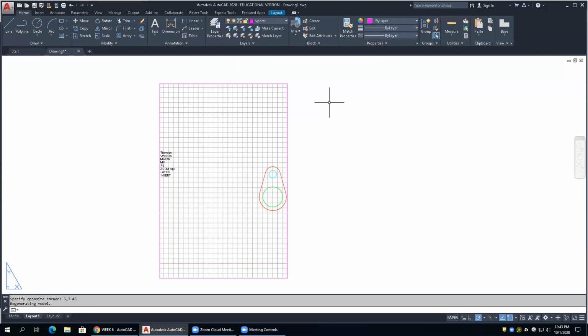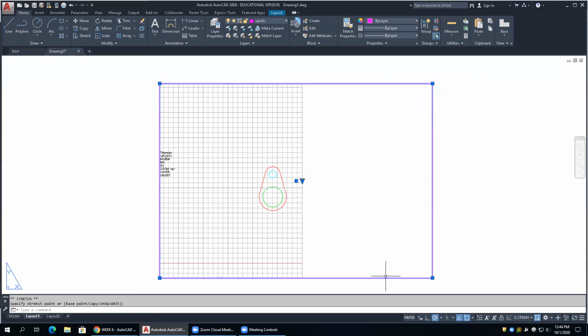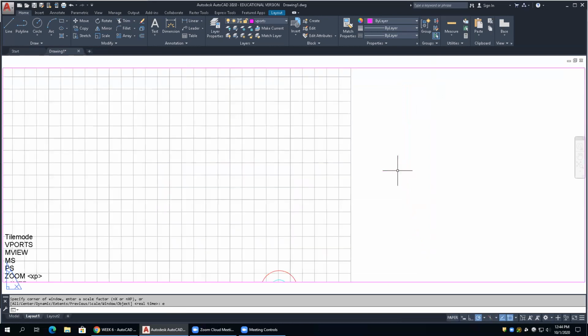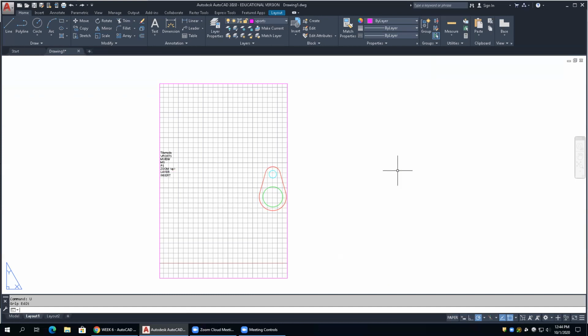Now, if you notice, if I try to select that object, it won't let me because that object is in a different dimension. Okay? It's kind of like you're looking through a pane of glass and the object is behind the glass. Now, the object that's actually active is the viewport itself. So notice, you guys don't do this, but if I click on that viewport, I can edit it. I can make it bigger. I can make it smaller. I can move it. I can do all kinds of cool stuff with that. Okay? So we're not going to do that. We're going to leave that alone. All right, is everybody good with that?